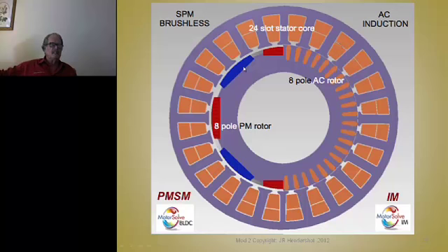The circuit is magnetized by the magnets, those magnets we bought, so we get that free magnetic circuit excitation for free from the magnets. So we don't care if the air gap's a little bigger. We're going to show you later what the effects of that air gap are. All it means is if I could make the air gap twice as big, I just got to make the magnet a little thicker, that's all. And I get the same flux.